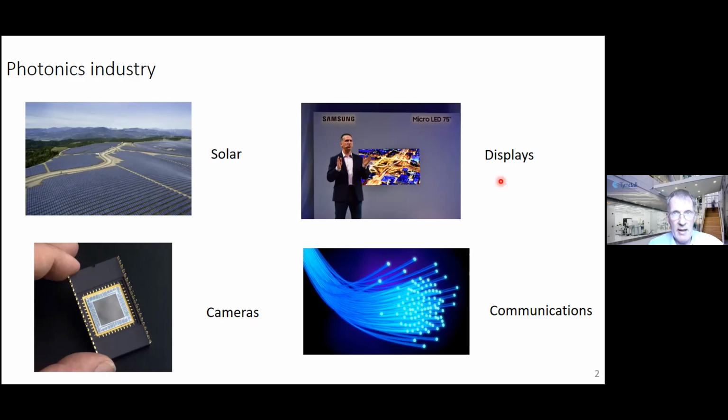They had the plasma displays, and then we moved to liquid crystal displays backlit by halogen lamps and mercury lamps. Those lamps were then replaced by LEDs, and now we've moved to a new material called organic LEDs. We're looking at quantum dots as down converters, and the latest technology that's on the way, and that we're heavily involved with, is in making micro LED displays.